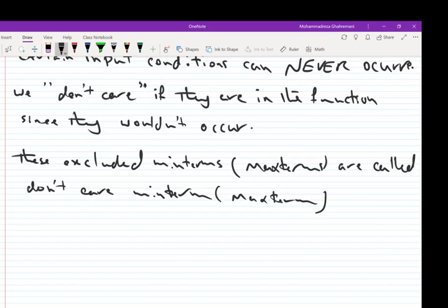What about the K-map? If we have these conditions in the K-map, what should we do? Regarding the grouping of min terms or max terms, grouping ones or zeros, because these don't cares in fact we don't care if they are 0 or 1. We say that these don't cares can be grouped with other min terms to form a larger group.